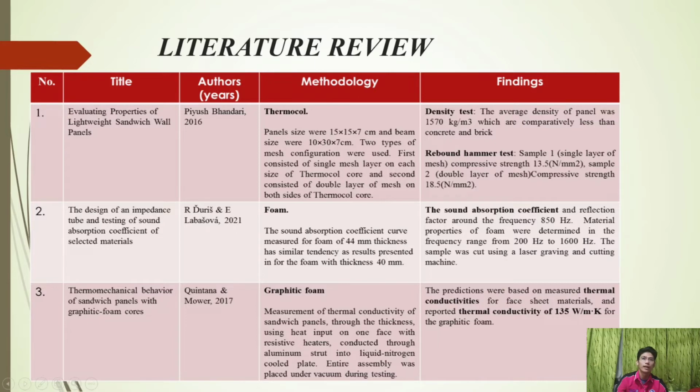Authored by Quintana and Mower, 2017. Graphitic foam: they measured the thermal conductivity of a sandwich panel through the thickness, using heat input on one face with a resistive heater, conducted through an aluminum strut into a liquid nitrogen cold plate. The entire assembly was placed under vacuum during testing.